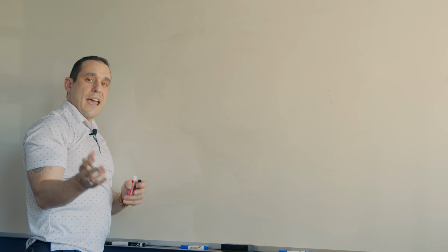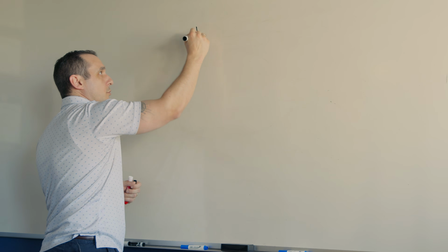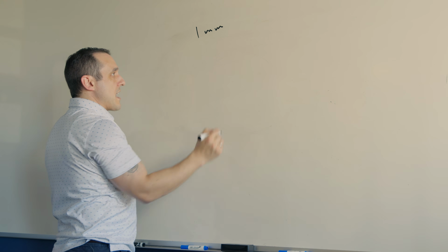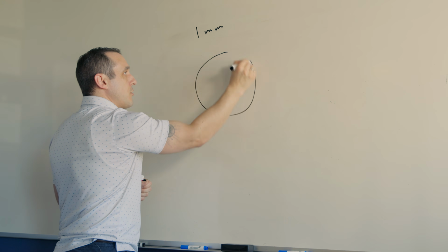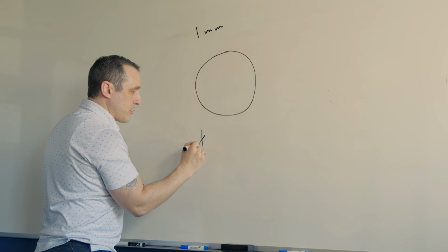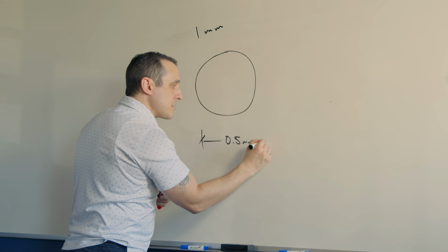How does this relate to solder mask and non-solder mask defined pads? Well, let's hop onto the whiteboard and we'll see exactly what these pads are and how they relate to the data in this table and how this all relates to via in pad. So now let's look at solder mask defined and non-solder mask defined pads, and we'll do this again for our hypothetical 1mm pitch BGA footprint. So in this example, we're going to have some pad that is going to be used for soldering the BGA, and according to the 7351 standards, this should basically be about 0.5 millimeters in diameter.